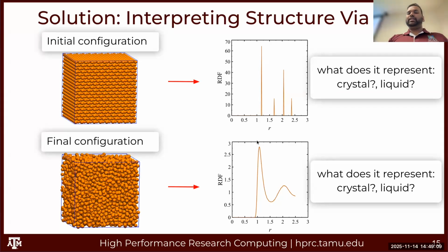This is the first shell, within a certain distance, and then it goes down, and then there is another peak at a certain distance. There is some favorable interaction, and then it decays and goes to 1 at long distances. Now, LAMMPS by default computes only until your cutoff, which is 2.5. You can also write a separate code to compute until longer distances if you want to see the value going to 1.